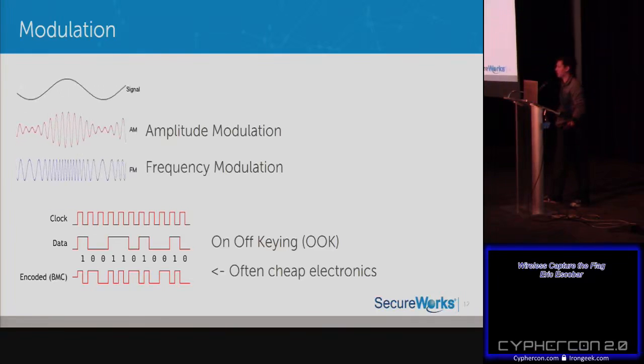Going into how all of these electronics work, the reason they do this is because your radios can be really off. They don't have to be tuned super precisely. You don't really care about interference, because you retransmit the signal probably 5 or 6 times when something gets triggered. For example, with a motion detector, you wave your hand in front of it and it will trigger 6 times instead of just once. That's basically to do with interference. It's a really cheap, easy, dumb way.